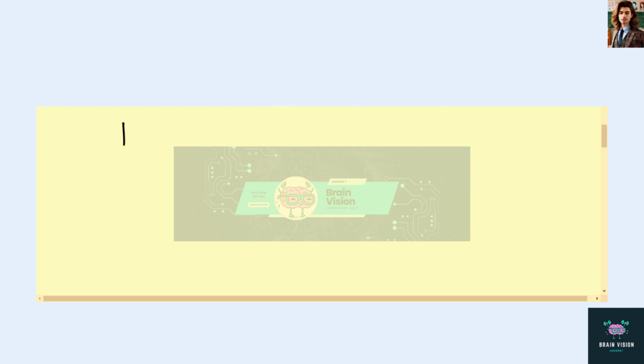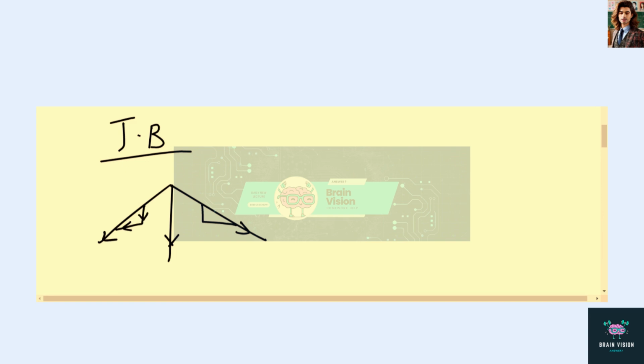Now we can look at another joint. Let's take joint B, JB for short. We have this force coming like this, this force coming straight down, and this force. Now, check the diagram and use the dimensions given in the diagram. You will have this angle to be 45 degrees.